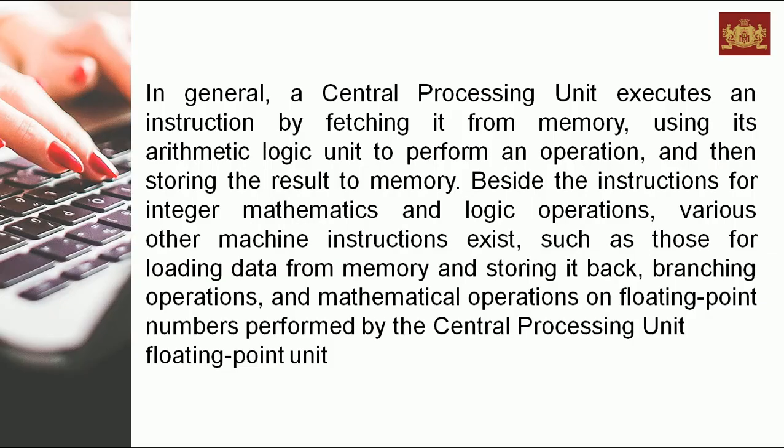In general, a central processing unit executes an instruction by fetching it from memory, using its arithmetic logic unit to perform an operation, and then storing the result in memory. Besides the instructions for integer mathematics and logic operations, various other machine instructions exist, such as those for loading data from memory and storing it back, branching operations, and mathematical operations on floating point numbers performed by the central processing unit's floating point unit.